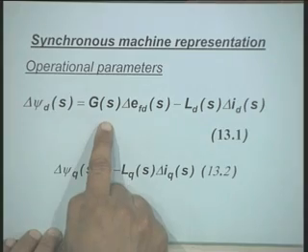You apply field voltage and vary the frequency of the applied voltage, okay, and measure the output voltage of the machine, and plot the gain versus frequency, that is, the applied voltage at the field winding and the output voltage at the terminal of the synchronous generator for a range of frequency, right. Once you make this plot, this curve can be fitted with the characteristic of this G(s).